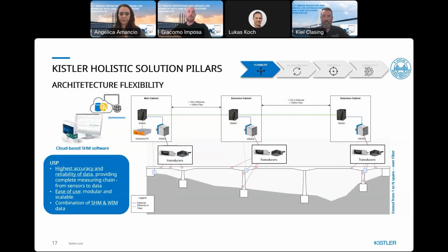Regarding architecture flexibility, because we need to address our solution to a really complex project like a bridge, our architecture is cluster-based. As you can see here, to keep the measuring chain as homogeneous and robust as possible in terms of data transmission, we define this architecture where every cluster has a limited number of transducers located at strategically placed points on the bridge. They are connected to the KiDAC, and in each cabinet, in each cluster, we have a switch. Then all this data is sent to a master cabinet where the industrial PC is located, which processes the data and sends it to the cloud.